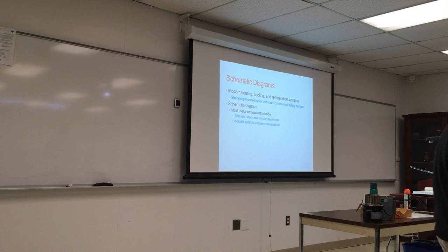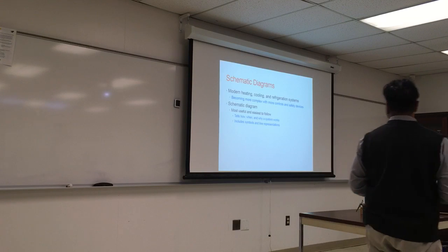Some schematics are colored, some of them are not colored. So you have to rely on what it says at the beginning of the line. Is it line voltage or is it neutral? Some schematics are colored, which is easy. Some of them will even say the color on the wire, even though it's printed in black, it will say purple, blue, or green.